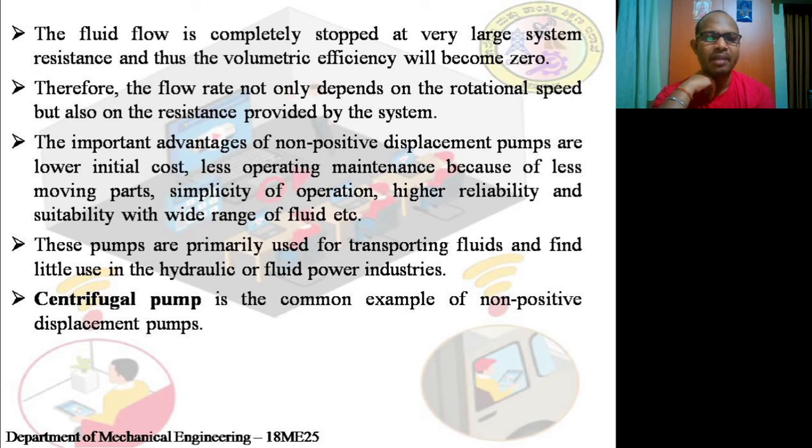These pumps are primarily used for transporting fluids and find little use in the hydraulic or fluid power industries. Centrifugal pump is a common example of non-positive displacement pumps. Centrifugal pumps come under the category of non-positive pumps, which are also called hydrodynamic pumps.